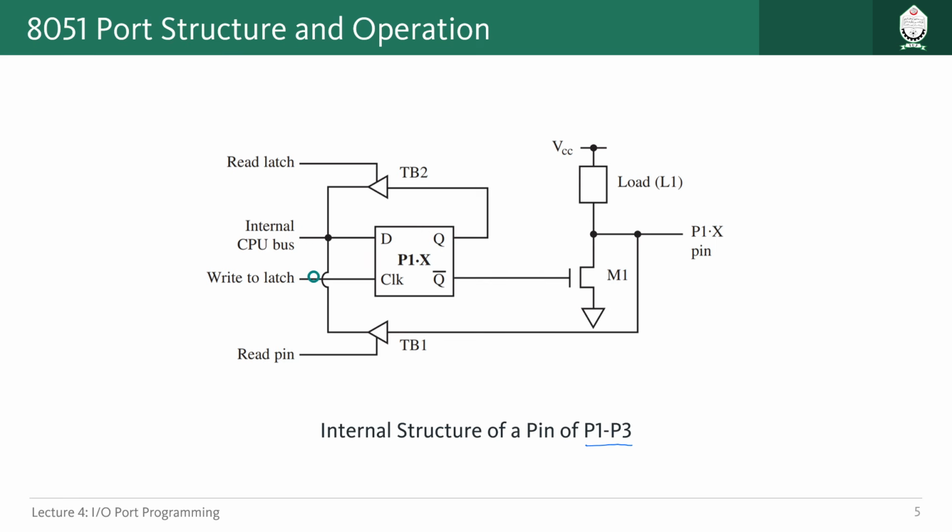Basically, whenever you write anything to the port, like if I write a command such as SETB, what is happening is we are going to get logic 1 at this point from the internal CPU bus.